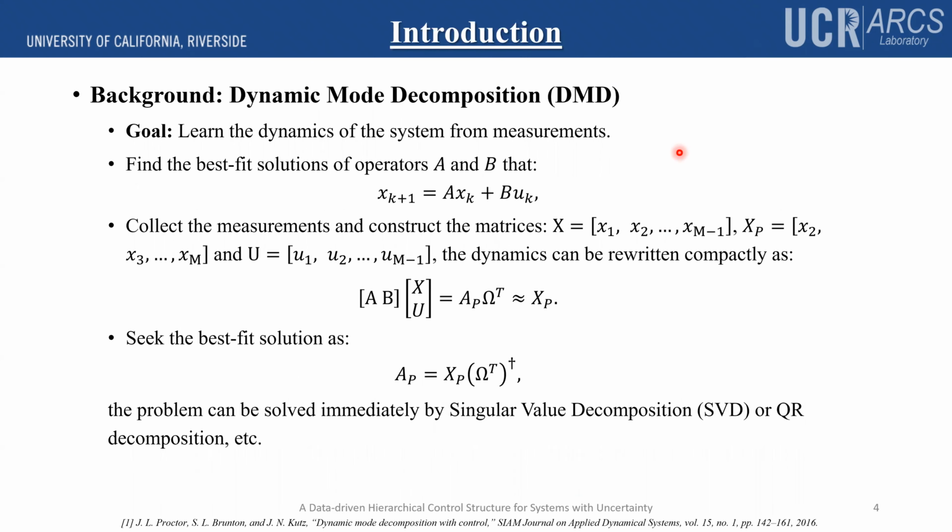Here, I will give a short introduction to the one we want to use in our structure, the dynamic mode decomposition. It is a way to learn the unknown dynamics from the measurements, so we could predict the states at the next time using current states and input. The key idea of this approach is to learn a linear approximation of the original system.